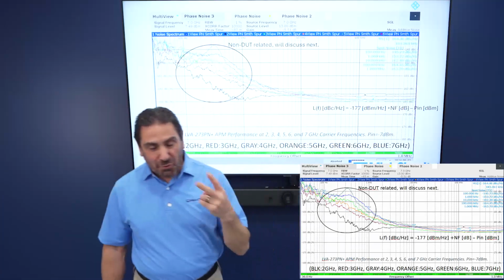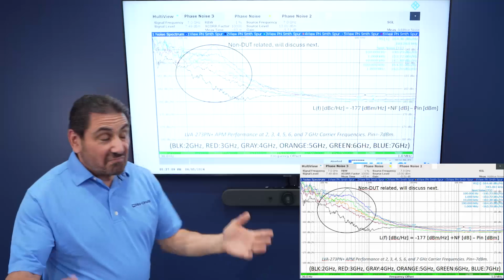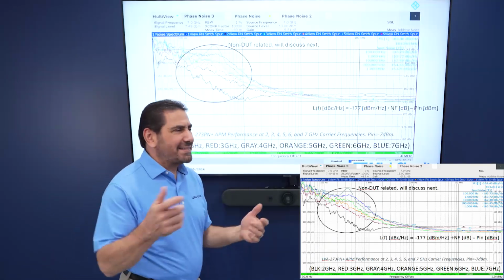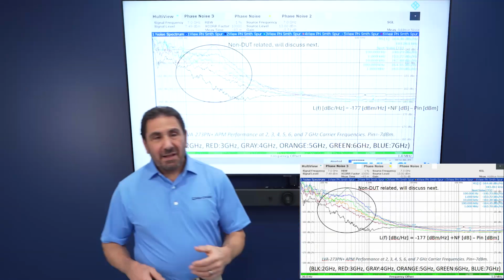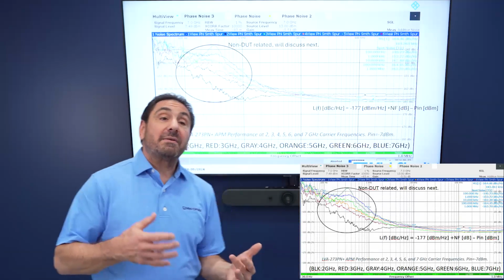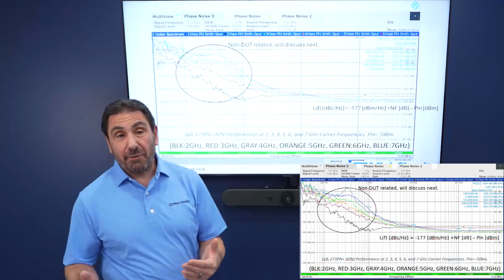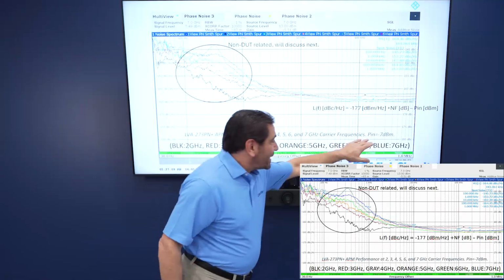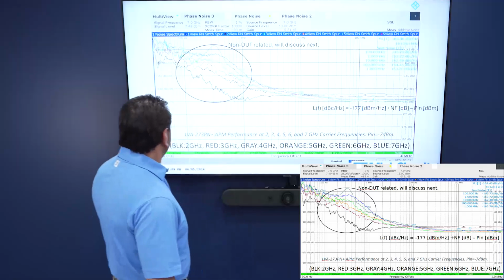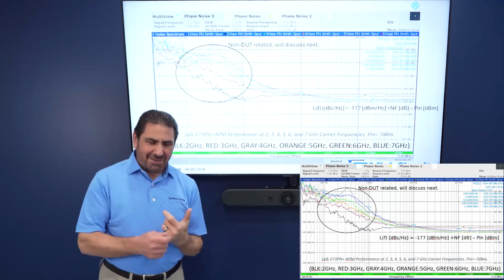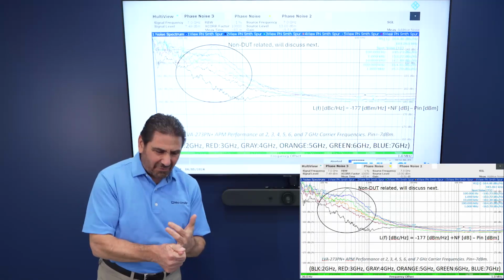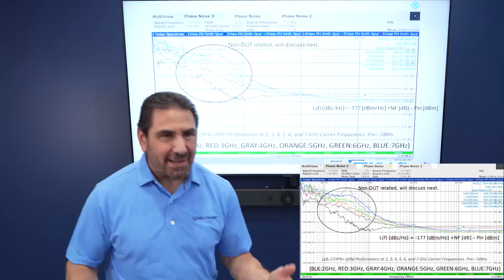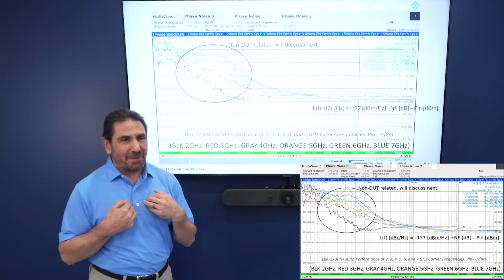And this brings up 2 interesting points. I get a call, measure the additive phase noise. I'm lazy that day, I'm gonna measure it at -7. The customer doesn't say, oh, I want the additive phase noise measured at a specific power. All right, so we ended up, wouldn't do this really, but we ended up measuring at -7. I get -162 at 10K. Now I'm gonna tell the customer I have an HBT distributed amplifier that achieves -162 dBc per hertz at 10K, then I'm gonna buy it. And I'm gonna look pretty stupid.